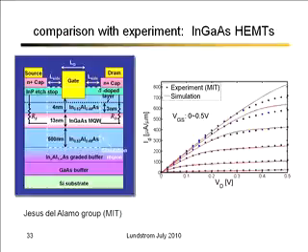But if you take a look, what you're seeing here are measured characteristics with the blue dots and a simulated ballistic simulation of the same device with the red. And you can see here that a III-V MOSFET, or this is actually a III-V HEMT, high electron mobility transistor, operates very, very close to the ballistic limit. If you were trying to analyze the IV characteristics of a III-V transistor, it would be much better for you to assume that it's ballistic. That would get you closer than to assume a textbook diffusive description.